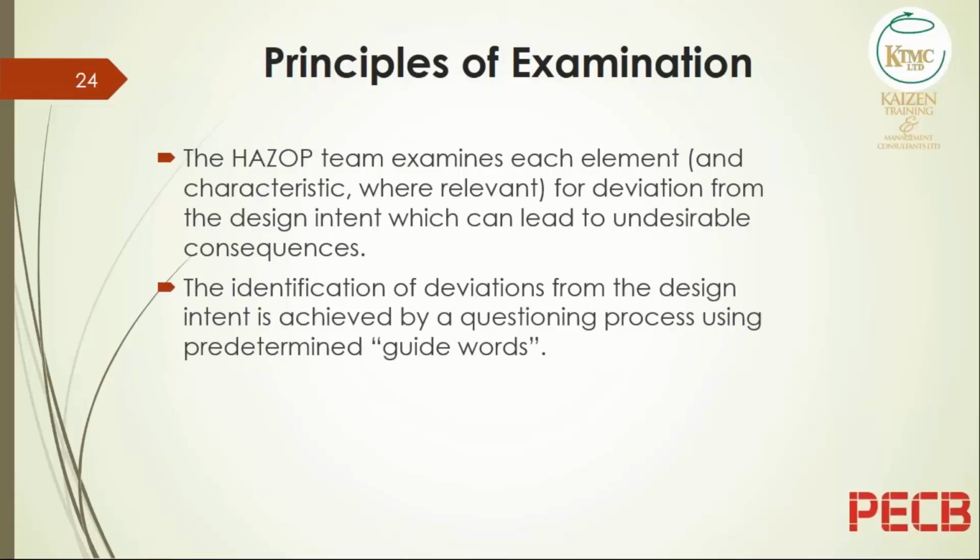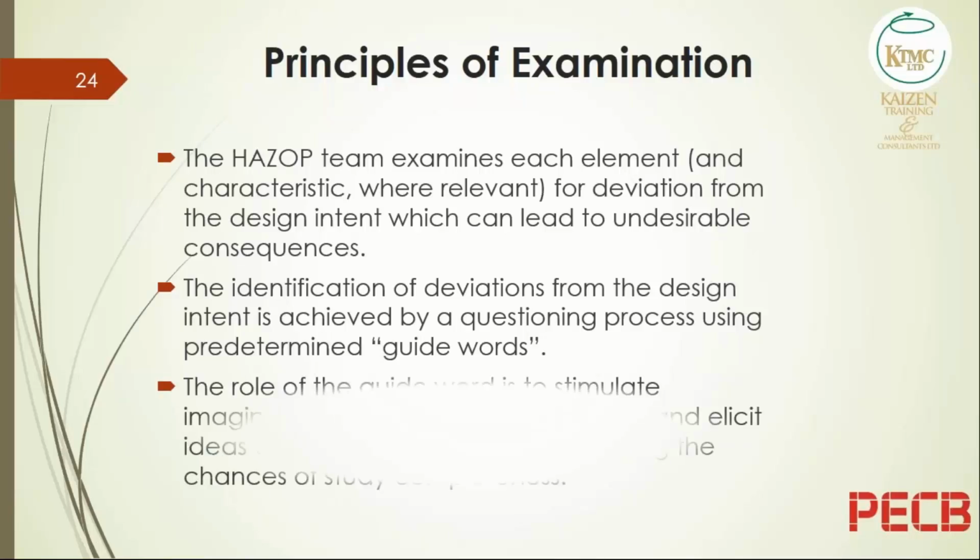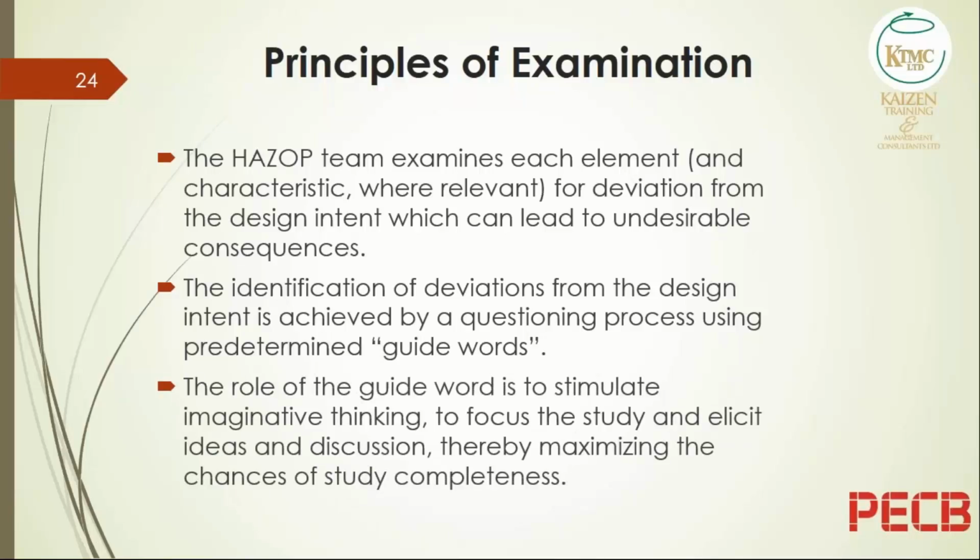The HAZOP team examines each element, and time is spent based on the importance or criticality, and we examine for deviation from the design intent, which can lead to an undesirable consequence. The identification of deviation from the design intent is achieved through a questioning process. This questioning process involves the use of the guide words. The guide words stimulate the thinking, the imaginative thinking, what could happen, and wild and wacky ideas are welcome. So it may sound within the realms of impossibility, but nevertheless, it is considered.